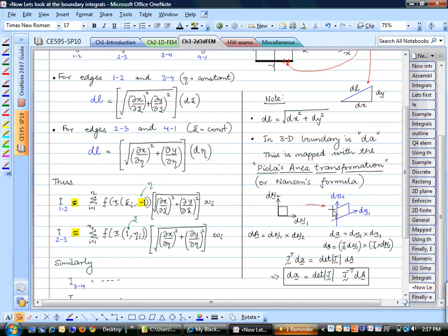If you deform that body, that area vector is going to get mapped to a new place, but you just cannot say that we will deform this with f. What happens is that these two vectors get deformed with f, or in this case it would be j. So dn1 gets deformed to this vector, and that vector can be calculated from this relationship.